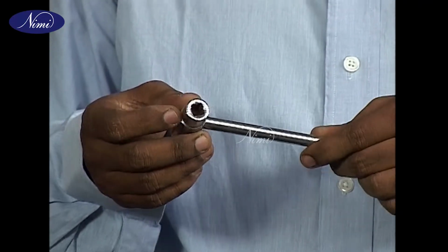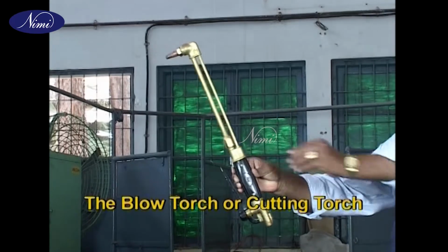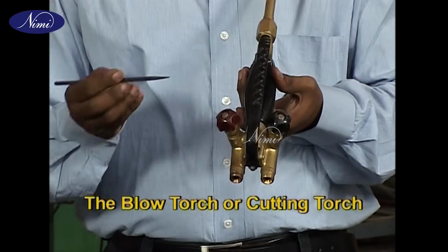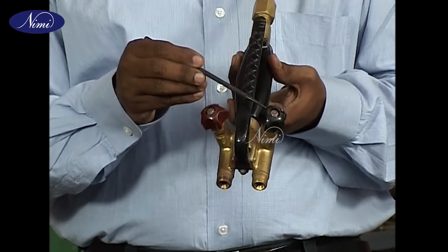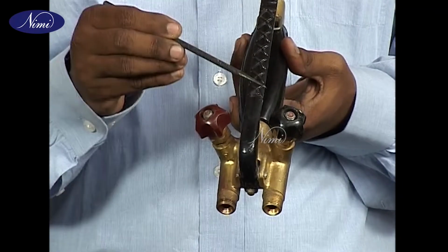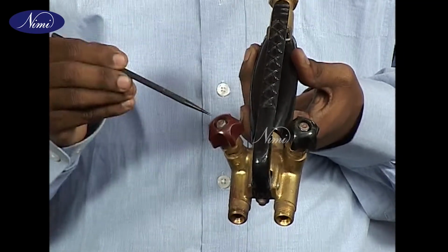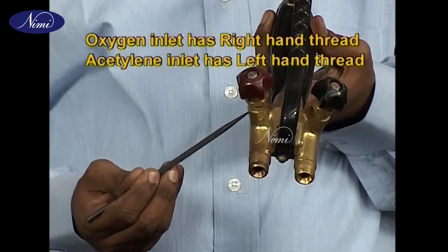After opening the cylinders, these keys should remain on the cylinder itself, so that we can quickly close the cylinders in case of emergencies. The blowtorch or the cutting torch. You can see two inlets with control valves having knobs, one in maroon color and the other in black. Through the inlet having the black knob, oxygen enters the blowpipe, and through the inlet having the maroon knob, the acetylene enters the blowpipe. Here it should be noted that the oxygen inlet has a right-hand thread and the acetylene inlet has a left-hand thread.